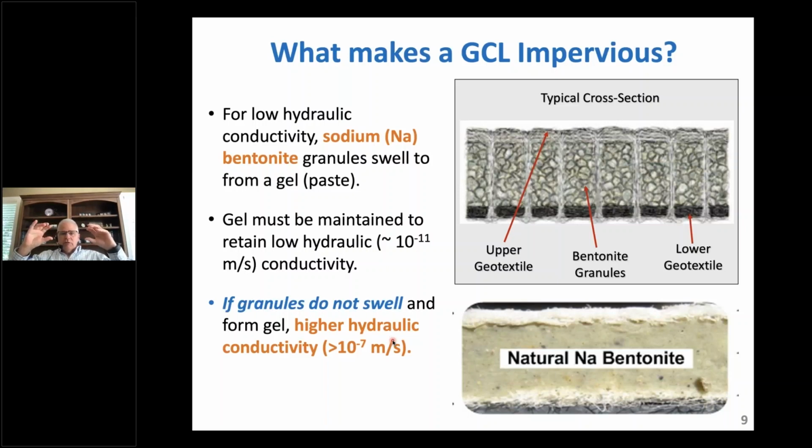with needle punching or stitching, but it's a granular material. That's what I show here in the upper right-hand corner in this figure. Now this is an artist's rendition, but whether I had a granular bentonite or a powder bentonite or some well-graded bentonite particulate in my GCL, it is a particulate, usually sand to silt-sized particles.